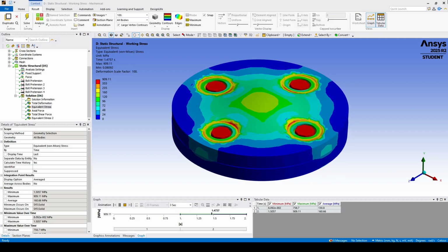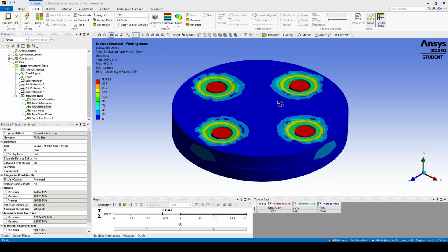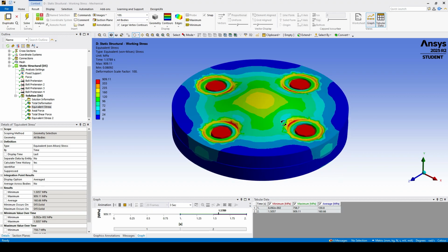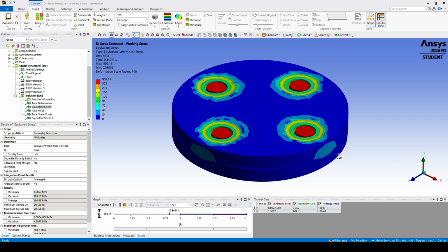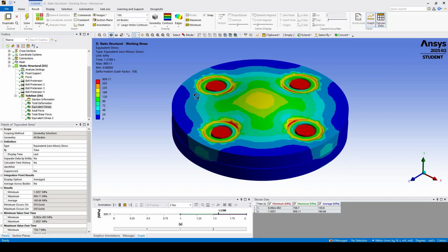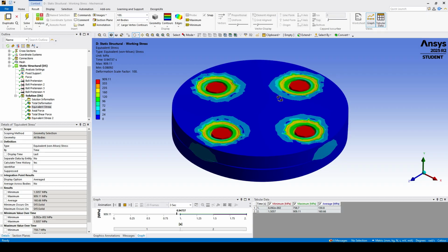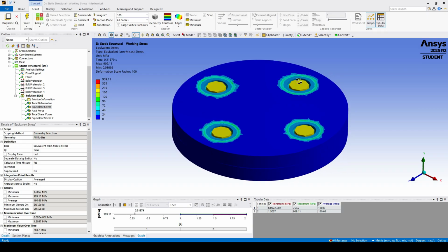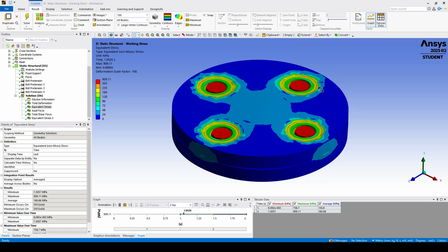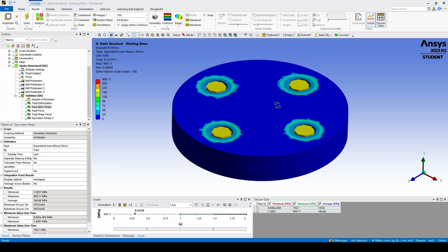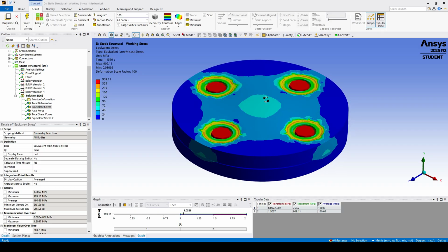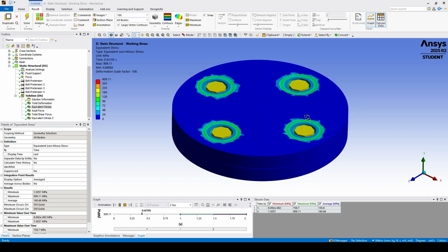So, this is the same bolted connection that we have been using throughout this series. It consists of two steel plates connected with 4 M8 bolts with a strength class of 8.8. Each bolt was preloaded with 18.6 kilonewton, and I initiated another simulation, but without bolt pretension, just to get only the external forces acting on each bolt.